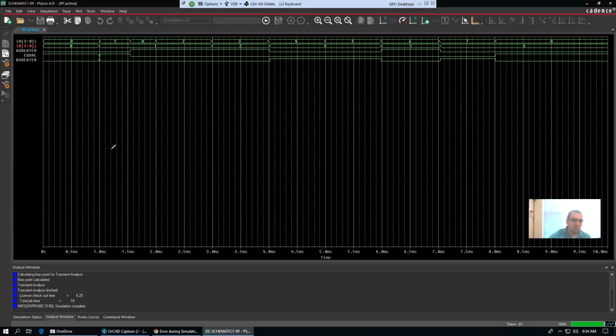And what you're going to notice here is when we have 0, 0, now you have 1, the equal here is 1, and the other output signals are 0, 0. So A greater is 0, B greater is 0, and equal means A equals B. Let's go now here.